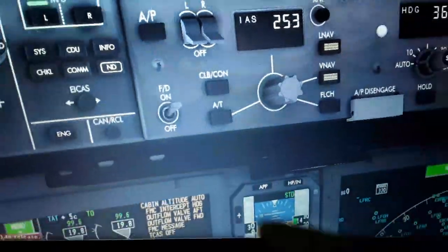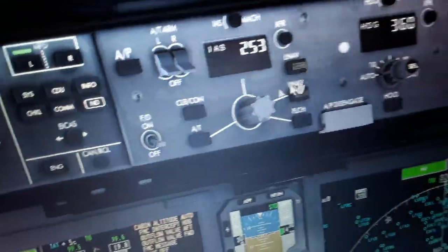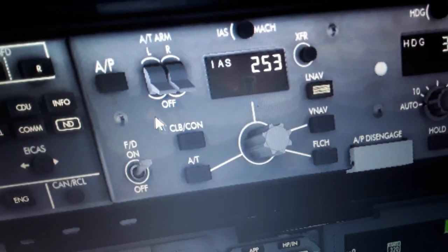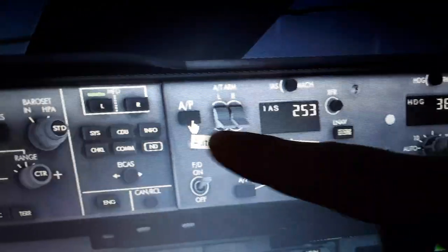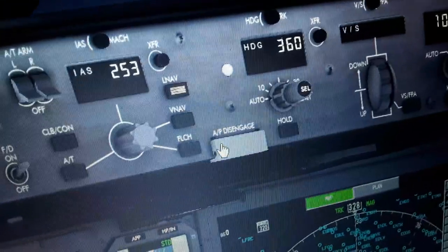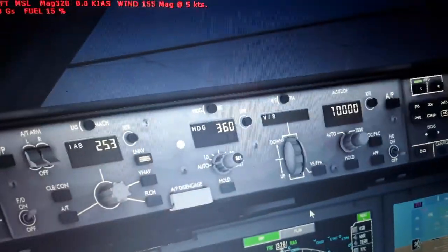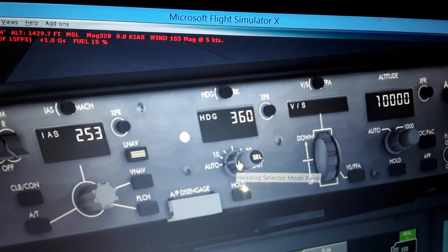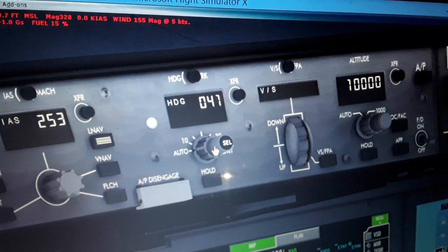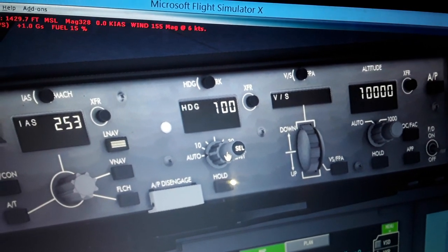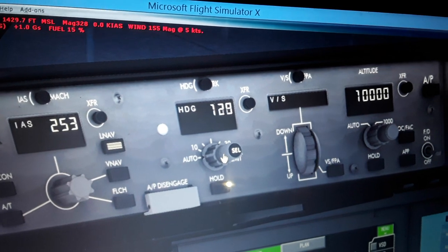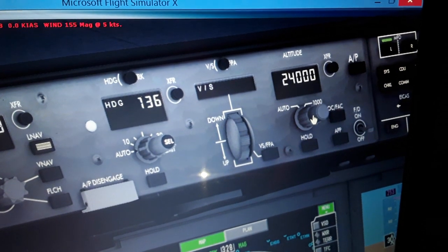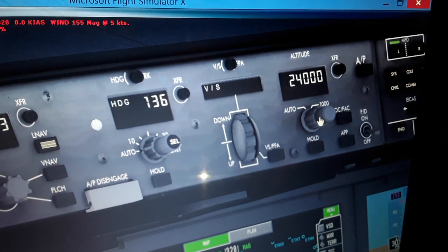The flight director, if we turn off the flight director, we cannot rearm any mode or the autopilot. We need the flight director on all the time. We can turn off mode. This is the autopilot engage, autopilot disengage over here. So this is the airspeed guidance, the heading and bank angle limiting flight. We set the bank angle limit, how steep turns. We're gonna set the heading 136 degrees magnetic north pole heading. We're gonna set the altitude thousands of feet over here, then hundreds, so you can set whatever you want.